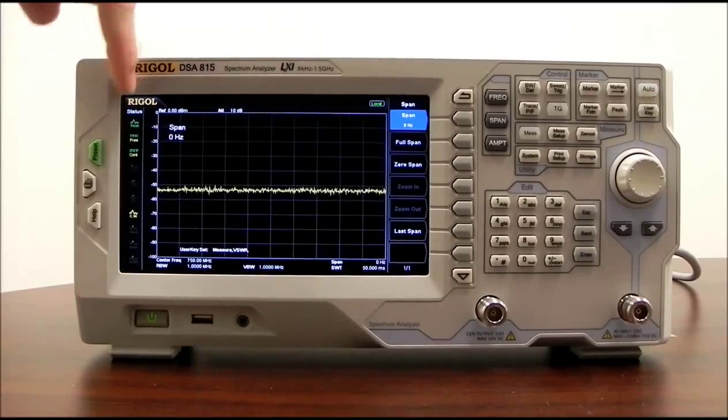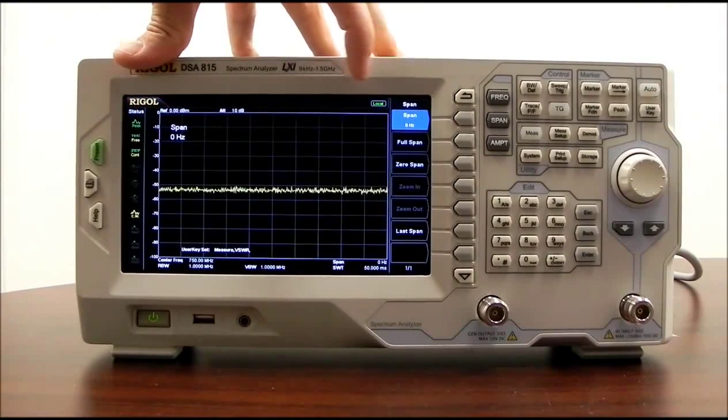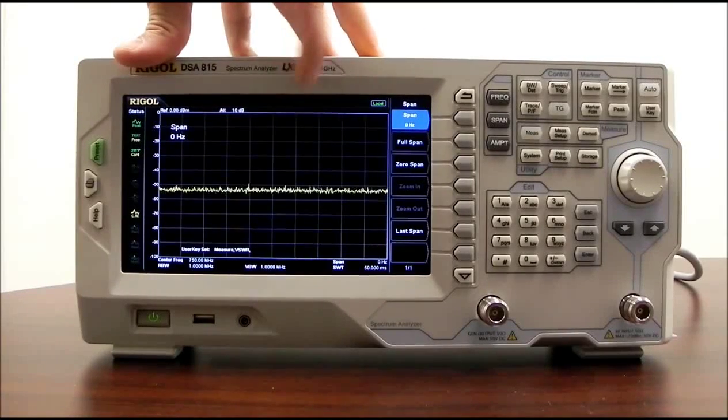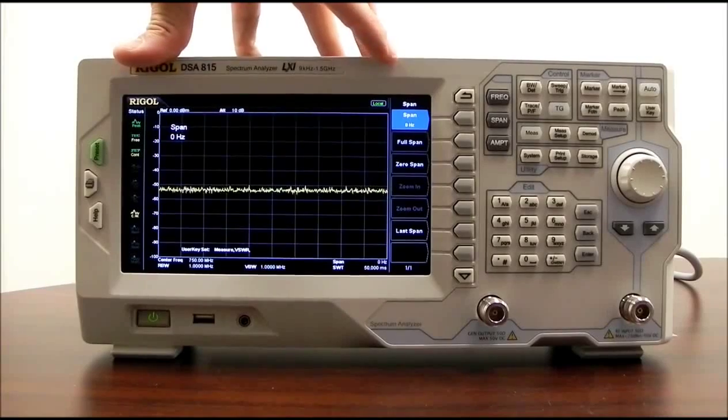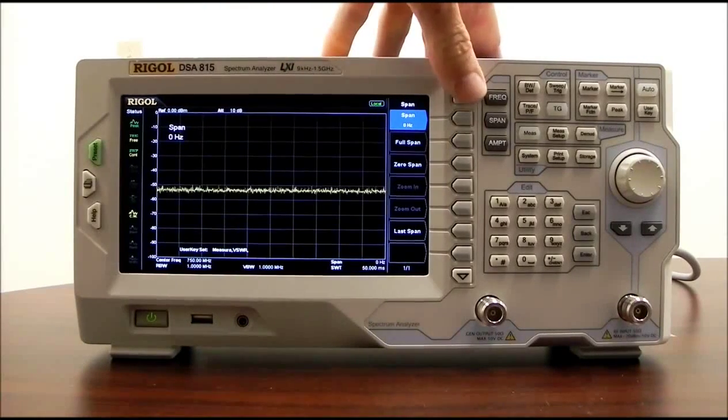And now this is with amplitude with respect to time. So you can actually look at time varying signals or the actual modulation of the signal at that particular frequency level. So you can think about it as a limited bandwidth, extremely limited bandwidth oscilloscope. Now you can use that if you have a particular code or something like that that's being sent at a particular frequency level or value. You can watch the actual bits, let's say, of that signal coming through, which can be helpful.